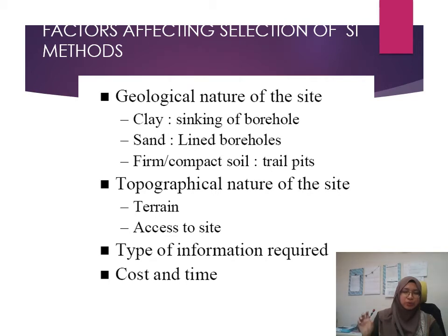So you have to check what is the optimum number of boreholes, and the type of method of exploration that suits the budget of the project. So it is cost and time. If you increase the depth of the borehole, it is costly and also time consuming. But again, this depends on your need of the project and also the budget of the project.